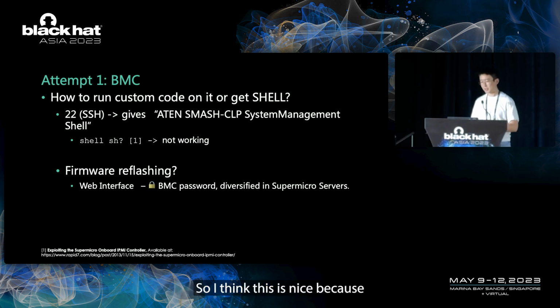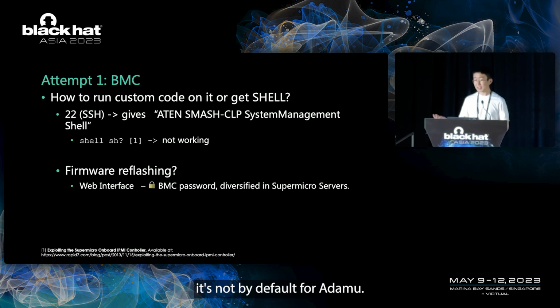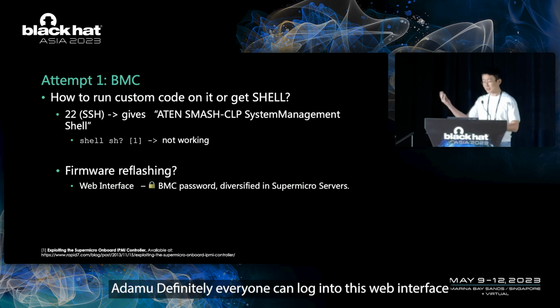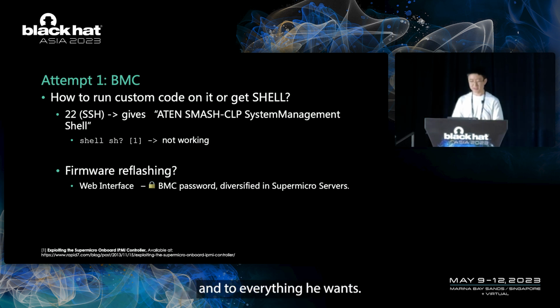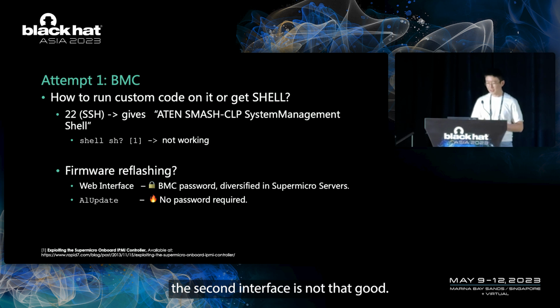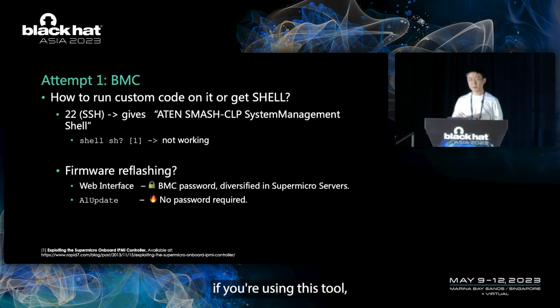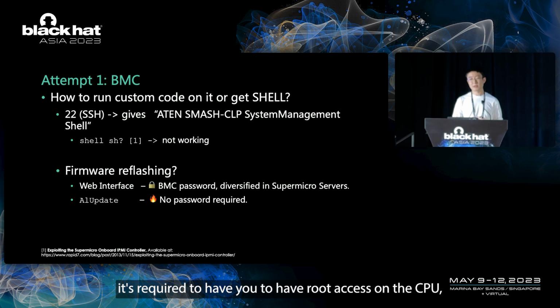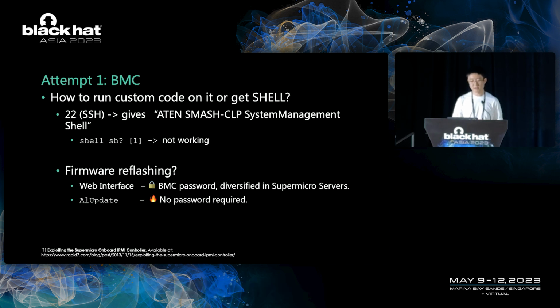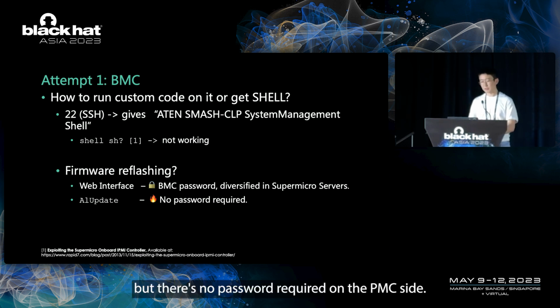I think this is nice, because it's not admin by default, which would mean everyone can log into this web interface and do everything they want. And the second interface is not that good. There is a tool called the update tool. It can be run from the CPU with that KCS interface. If you're using this tool, it requires you to have root access on the CPU, but there is no password required on the BMC side.